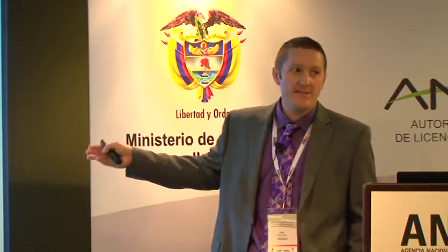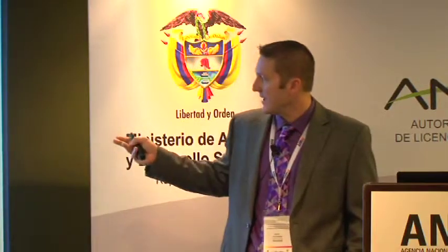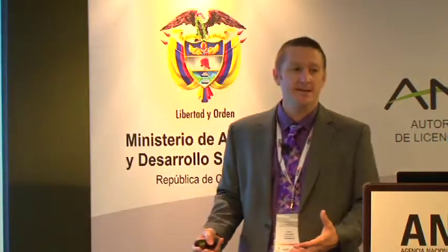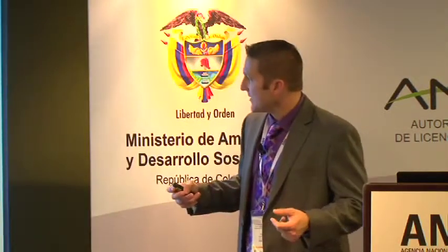We've seen tears in the liners in the fluid impoundments. Again, we're seeing the industry use more above ground storage tanks to minimize that potential for release. But even when you have tanks, you can have leaking valves. So we need to make sure they're getting inspected. We've had spills of diesel fuel and just fracturing fluids. Somebody drops a container of the fluids and it spills. That's why you need well pad liners and secondary containment. So these are pretty simple engineering options to make sure that these potential impacts are minimized.